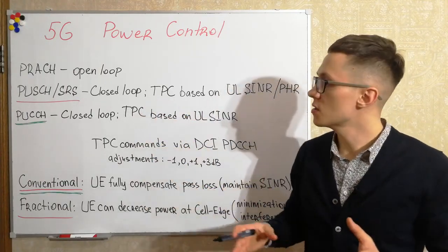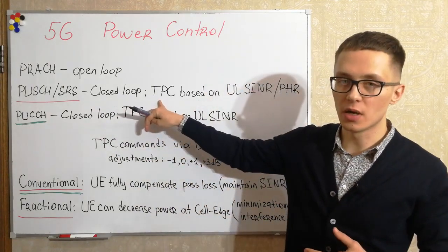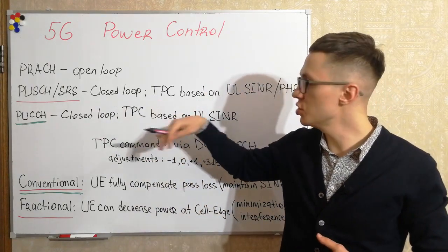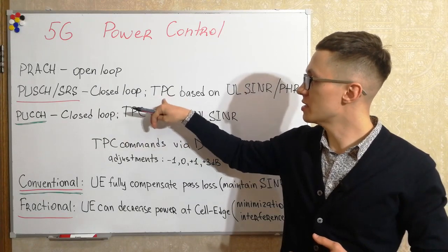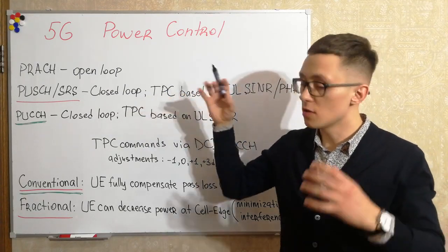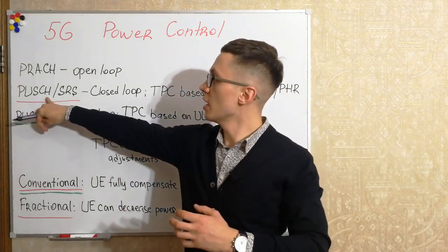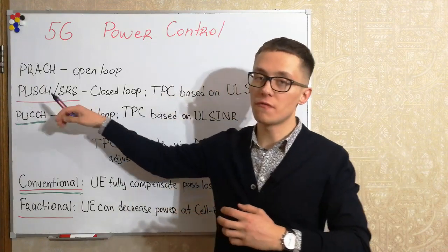For some cases, we can configure DCI commands via PDCCH. I mean TPC commands, and these power commands can be the same for PUSCH and sounding reference signals.